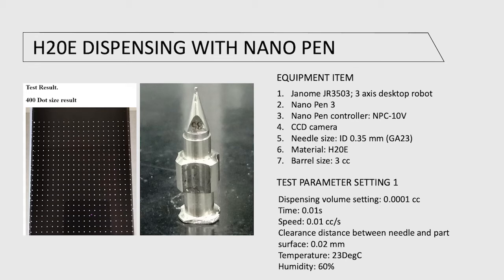We utilized a stainless steel tapered tip needle. That was a 23 gauge. The type of needle tip is critical for dotting repeatability. The common chamfered needle types tend to allow silver to build up or agglomerate in the needle tip. When silver agglomerates, it tends to back up the syringe, decreasing dot size, and eventually leading to bubbles or bursts.